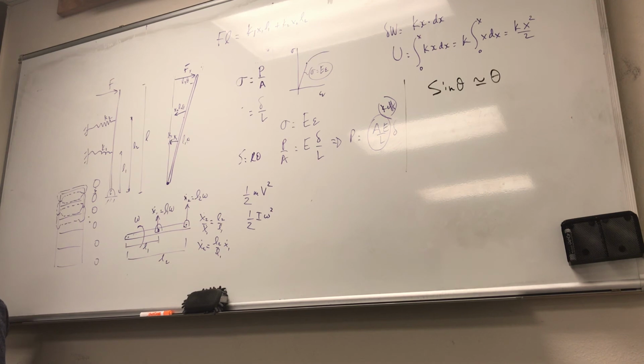Now you equate this to that, and then you say x equivalent is the same thing as x, and then you use theta dot, which is omega, equal to x dot, that is v, divided by r. Playing around, you will get that the mass equivalent is simply equal to m plus J0 over r squared.